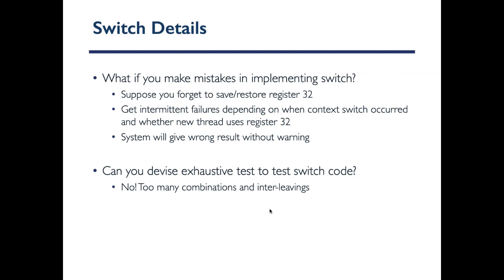Hopefully that was clear. Now, a few details about switch. It's something that many people consider very hard to code. It could be frustrating to implement this. We're going to give you the implementation of thread switch, although you will have to make some changes. But generally speaking, you have to make sure that you save and restore all the registers that are available. Let's say you have 32 registers. In our case, it's much less. In our boards, you have fewer registers to save.